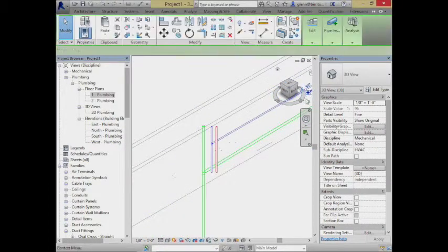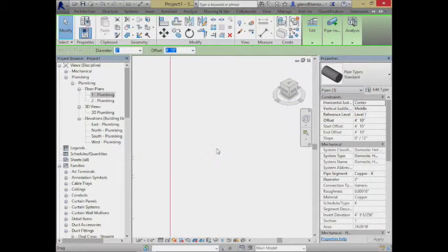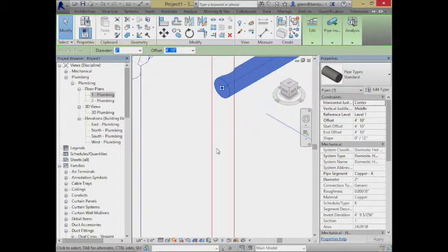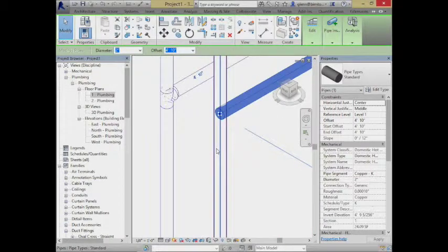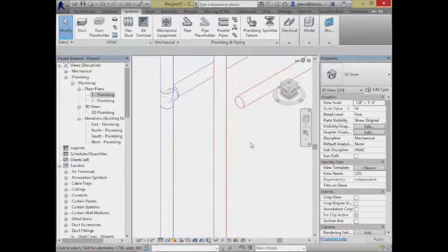Let's take this guy over here. Gonna pull it all the way down. See if I can get it to connect to that. Looks like it's not quite connecting to it. What's happening is it's a little bit offset, kind of in the XY direction. Just back that off a little bit. I could add another pipe connecting those things. So at this point, I can either move the riser to be in line with that, or I can add a short pipe segment from this end and tie it in there. Either way I would like.